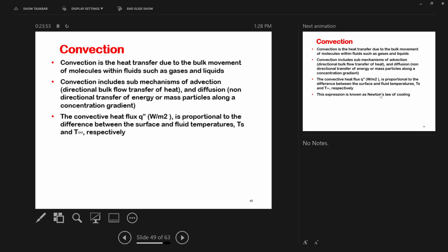Let's call it a situation property, right? It depends on your situation. And this is something that you have to calculate yourself. You cannot just measure the heat transfer coefficient of air on some surface and say this is the heat transfer coefficient of air everywhere. Okay? And to be able to characterize this convection, we have Newton's law of cooling.